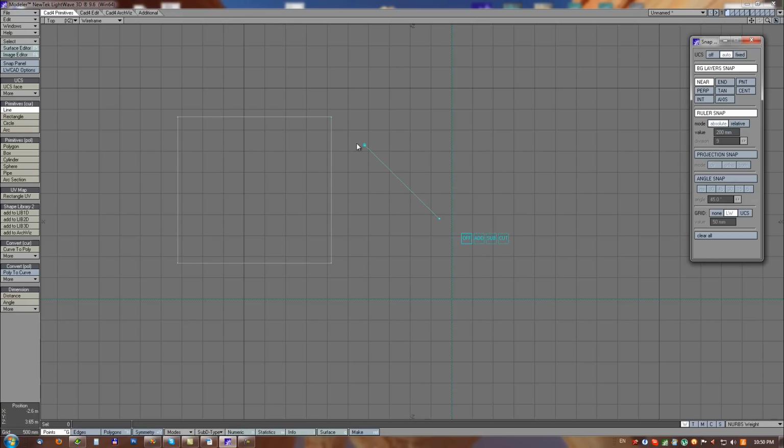When absolute mode is on, we can snap on ruler steps, and those ruler steps are always counted from one side of the edge. That starting point can be switched if I just click on the other side, and now the starting point of the ruler is on the other side. It is best to use it together with near snap for this side switching.